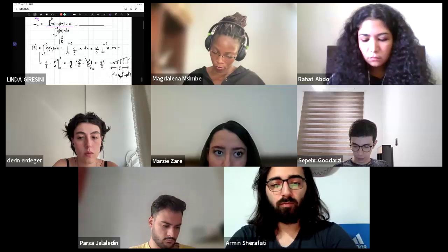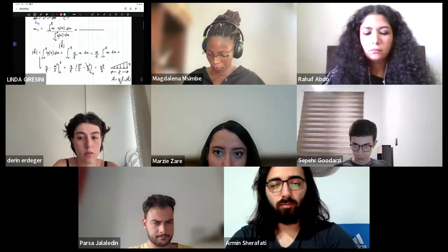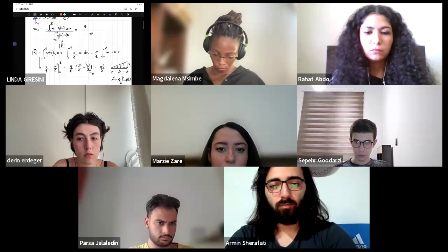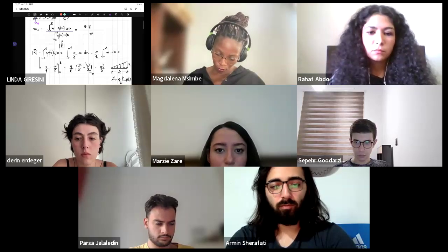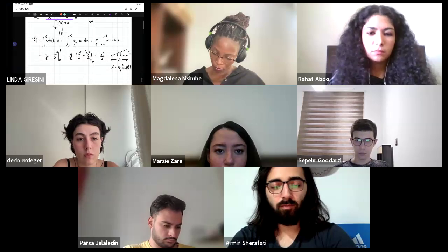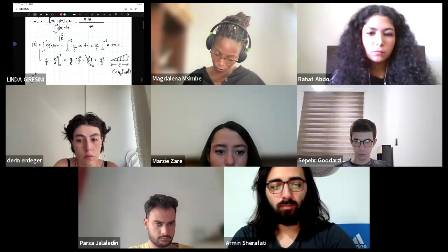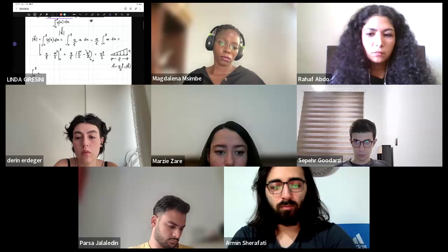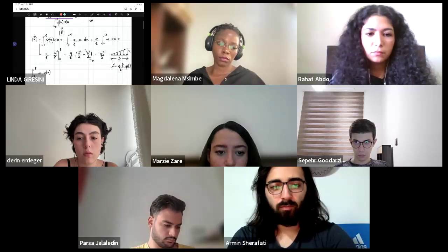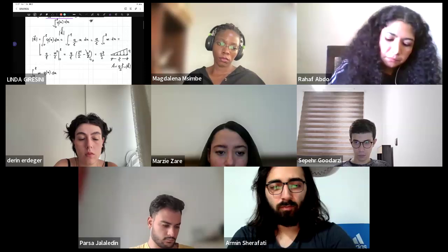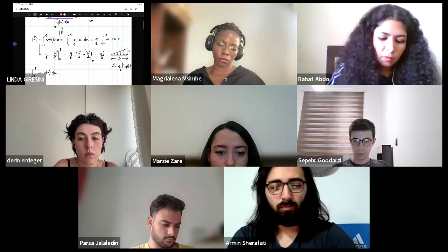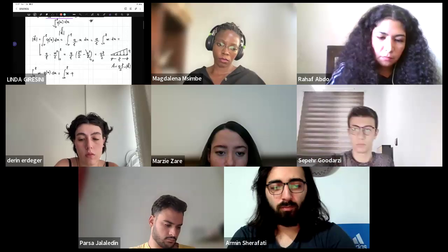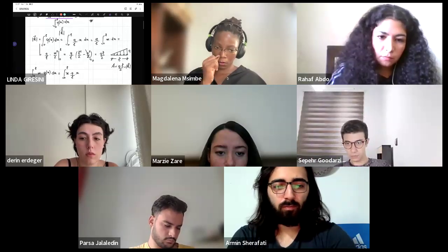Very simple. Now we have the denominator. So this part is known at the moment. So now we want to find the numerator here. So we want to find the integral from 0 to L of x times q(x) dx. We just substitute the formula q(x), which is q divided by L times x.